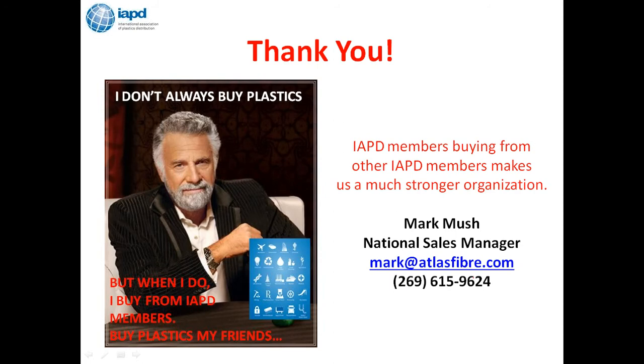Okay. How did a 3x4 become a standard size for G10 and the phenolic sheets? Well, it actually goes back to the cloth that's used for all these laminate products. The industry standard for weaving the cloth was standardized at about 50 inches wide. So everything that goes through the treaters and the presses starts out at 50 inches wide. From there, you can go as long as you want, but you are limited by the size of the press that you can build. The earliest presses probably were meter size. 39 inches would be the standard, but in the U.S., 3x4 just became the standard size because it was the easiest size to build the press to.